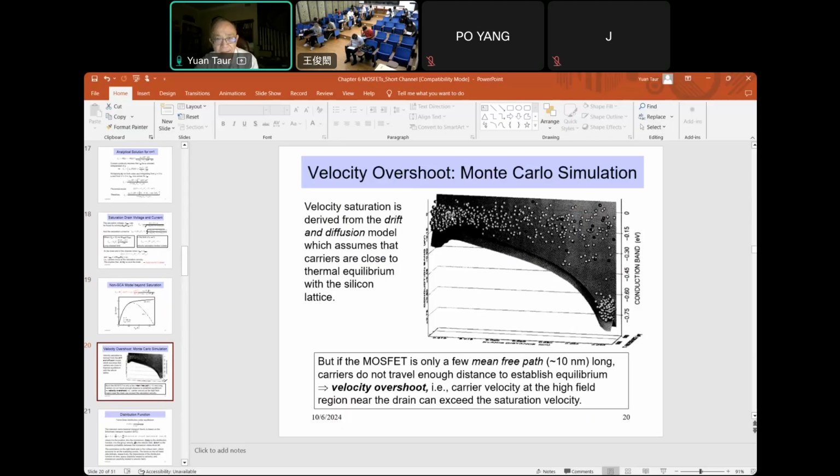And in the drift diffusion model, the carriers are supposed to take the lowest available state, which means right above the conduction band. And there's no state in the gap, of course, but once you're above the conduction band, there are lots of states. But in this case, you can see that the states are actually empty because there are no carriers. The carriers are occupying the higher energy states. Okay, so this is not in thermal equilibrium. We call these hot electrons. This happens when there are not enough collisions or not enough mean free paths between source and drain